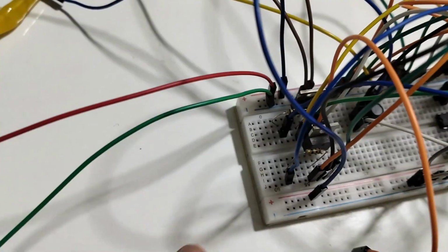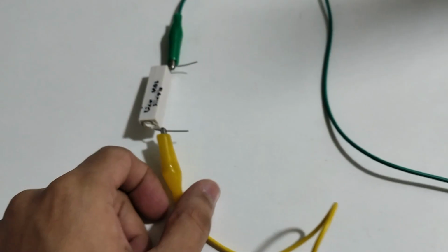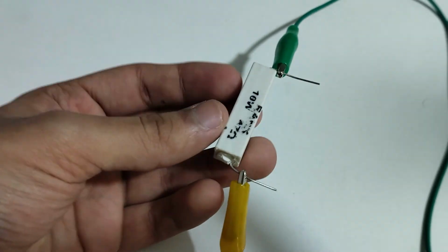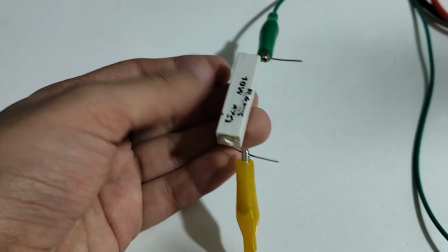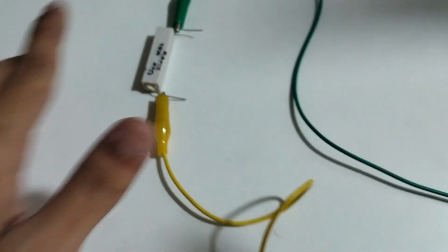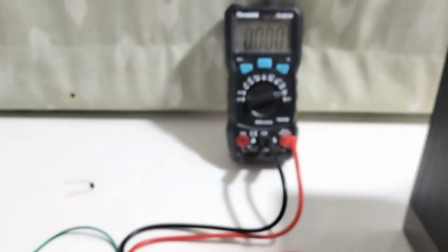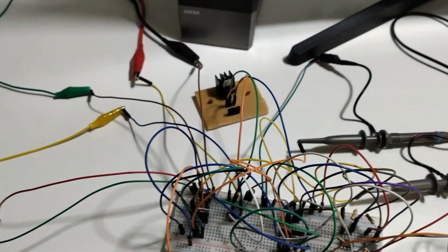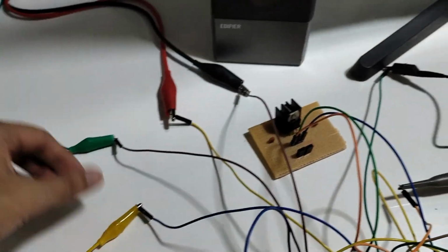And the load itself here, of course, these are a little big, so I can't really fit them on the breadboard. Ideally I should solder this, but nevertheless, I've just connected them using crocodile cables. So this is a ceramic or cement type resistor, 47 ohms, and it can dissipate 10 watts. So that's nice. It's a power resistor. We have the voltmeter here. You can see the output voltage, and one supply here to give the 12 volts. So that's the entire circuit. And a lot of probes and cables going everywhere. Just make sure nothing touches each other.